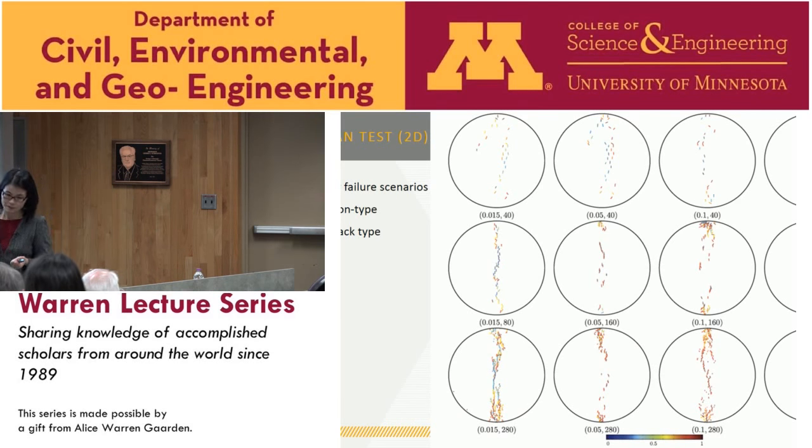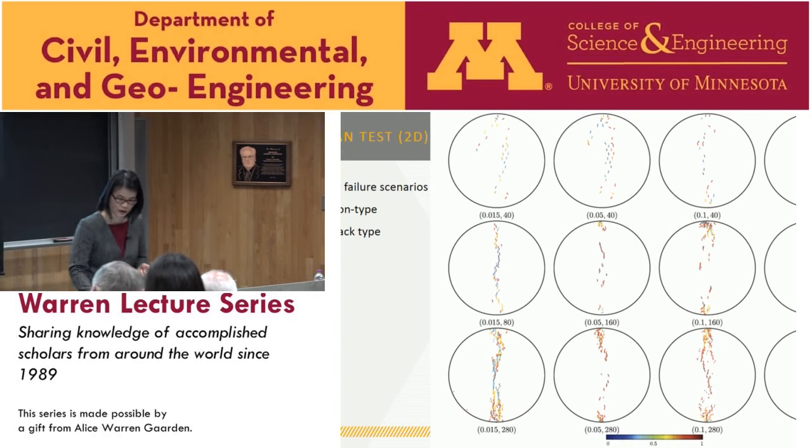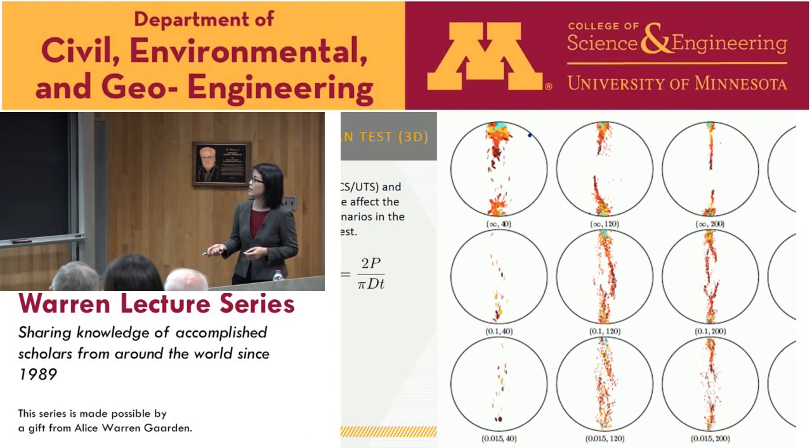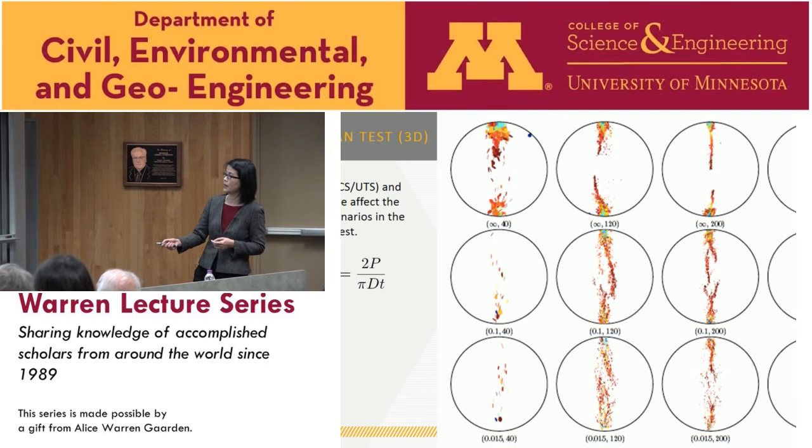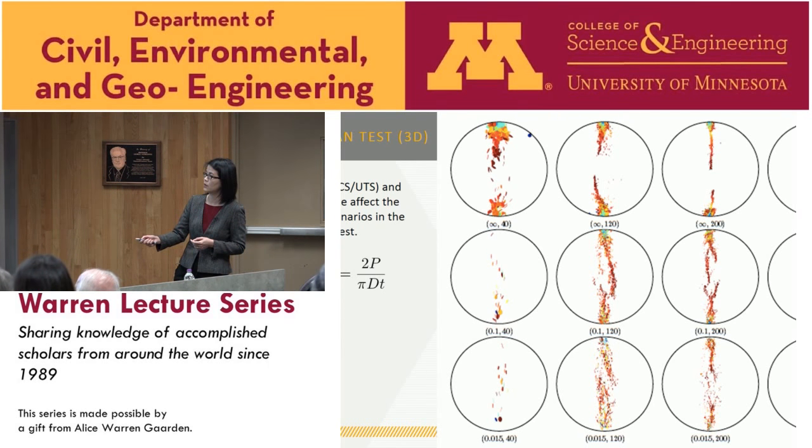So that's 2D simulation, and 3D is the same as well. When you have a lower beta, that means a high strength ratio, you have the center crack developed. All of them are plotted around the peak of the force displacement curve. Okay? And if you read this row, that is the simulations with elasto-perfect brittle contact laws, all of them you see driving from the loading area towards the center.